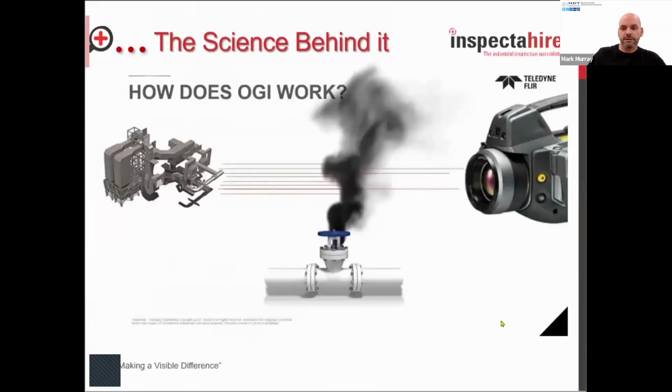So how does it work then? The gas cloud absorbs the radiation. Here's our radiation going through our gas cloud and into our camera detector. So the radiation is absorbed before it can get to the camera detector. So we are blocking that radiation from getting to the detector by the use of a filter.